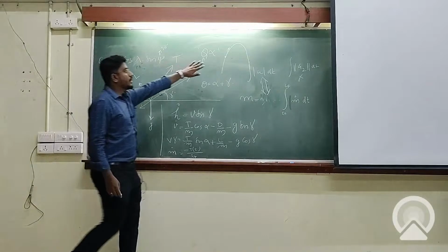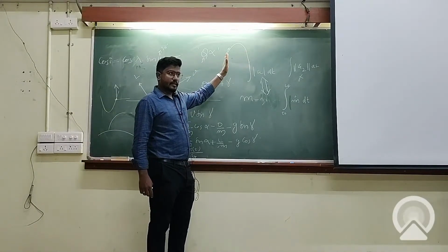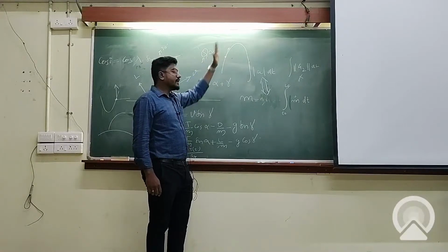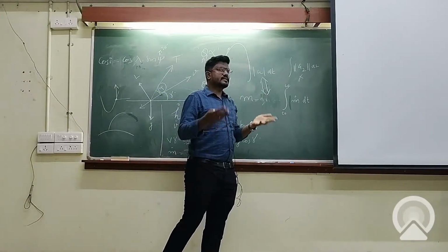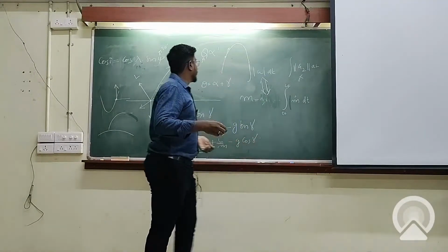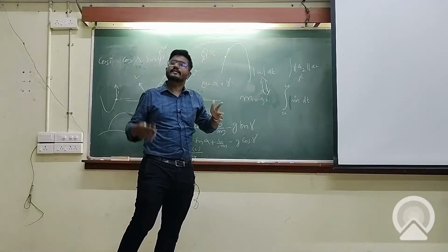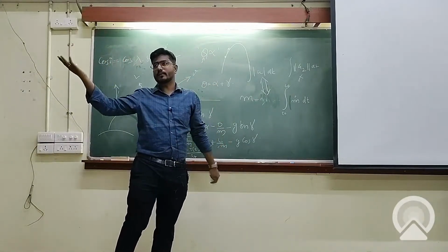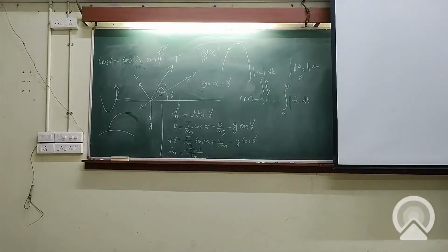So what we do is the second stage injects the ongoing vehicle in a suborbital ellipse in the ascending leg. The vehicle goes up on its own, and when the altitude and velocity states are favorable, we ignite the ongoing stage. That way, we get the altitude gain for free. At the expense of velocity, yes, it's actually gained in the ongoing stage, but altitude gain is more expensive than velocity. So that's about the coast phase.